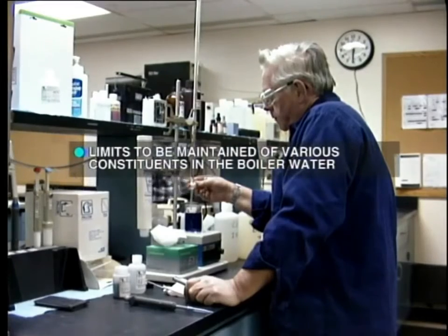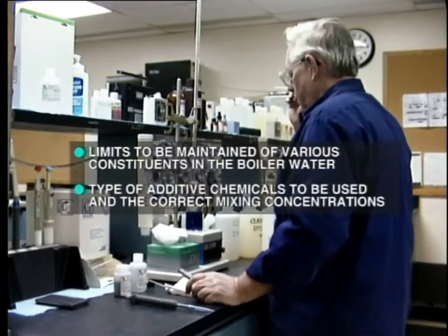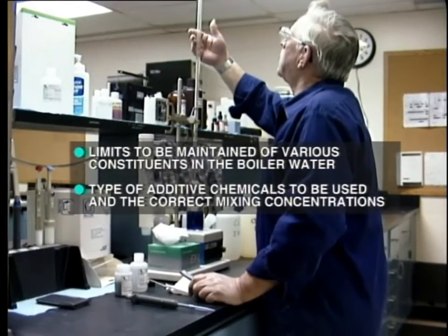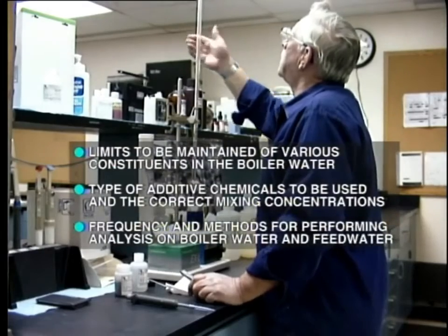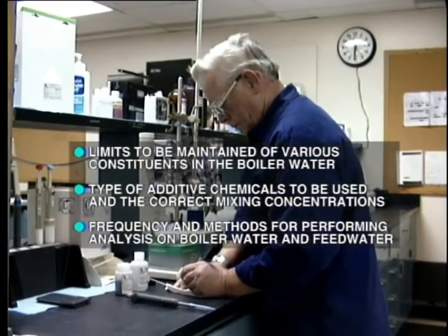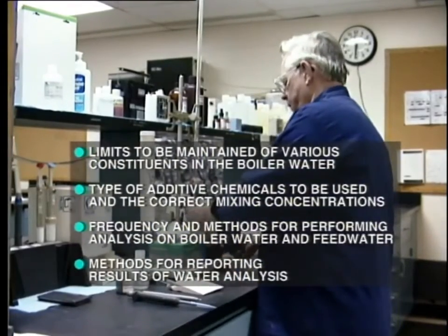it does require experienced water treatment specialists to establish the procedures for your particular boiler. Now, this will include the limits to be maintained of various constituents in boiler water, the type of additive chemicals to be used, and the correct mixing concentrations, the frequency and methods for performing analysis on boiler water and feed water, and the methods for reporting results of water analysis.